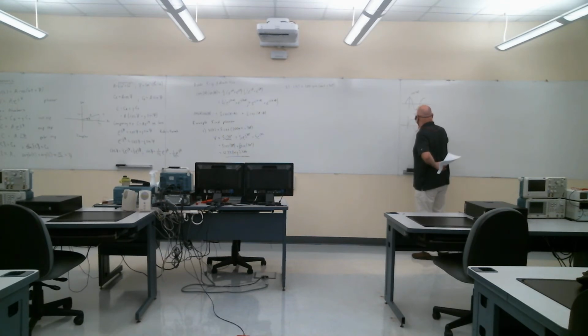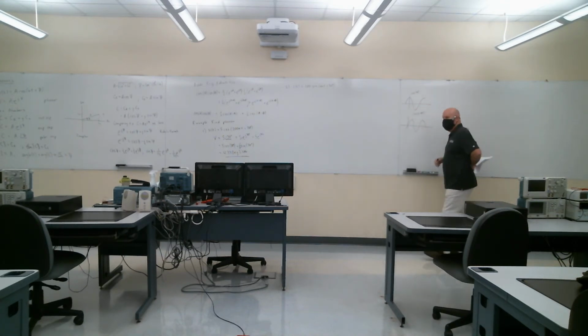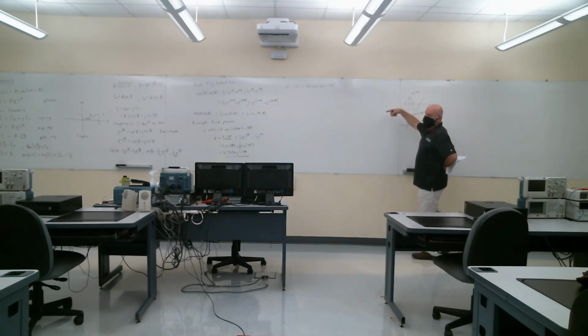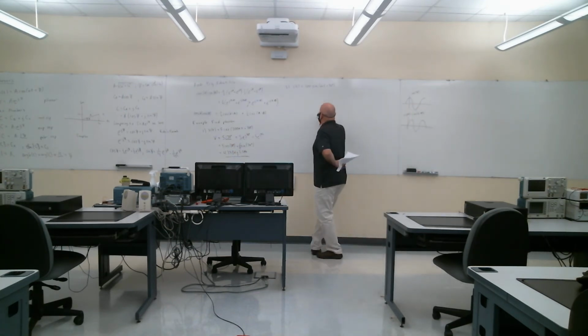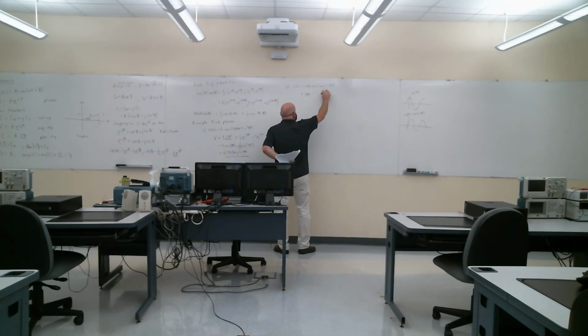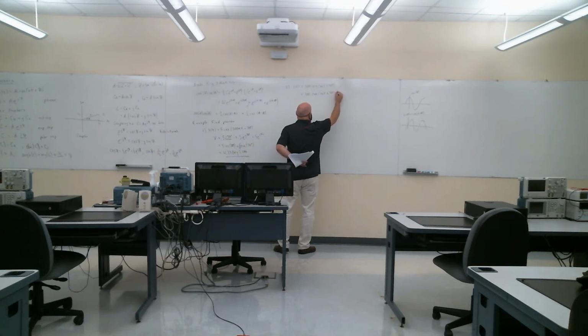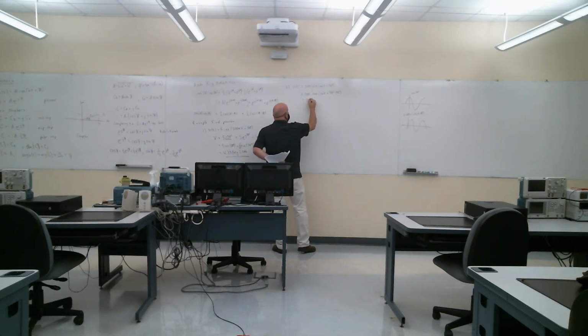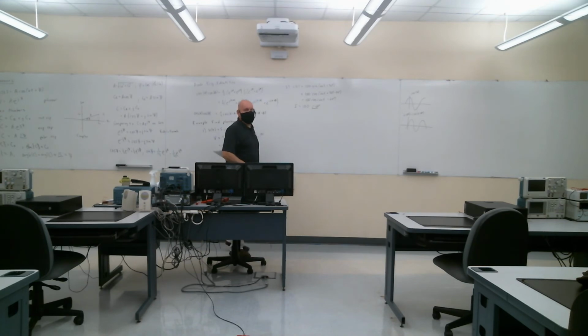So now what's this? That's a sine, right? Now actually if we added 90, you actually get the negative sine, so be careful. Sine of theta. So I have to use that little trick first. Sine of this is actually cosine of this minus 90. Okay, 100 cosine omega 0t minus 60 degrees. So the current phasor in polar form is 100 at minus 60.